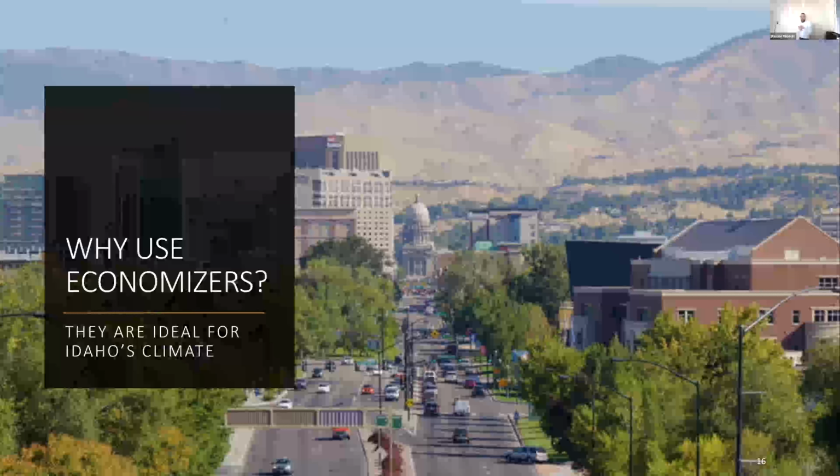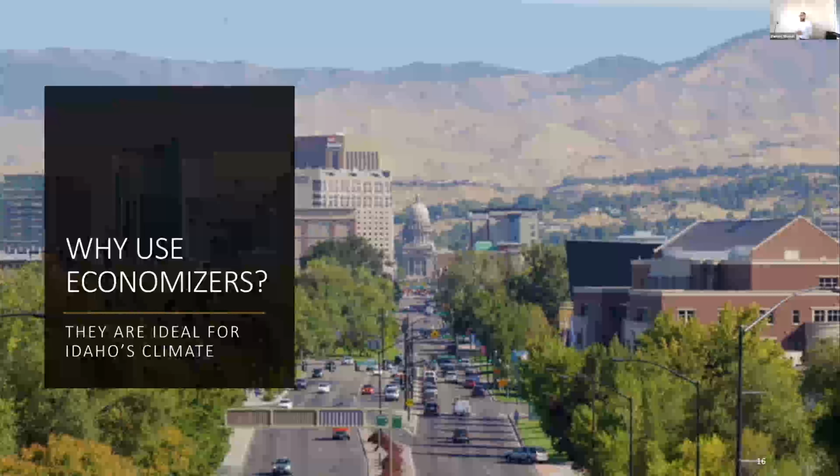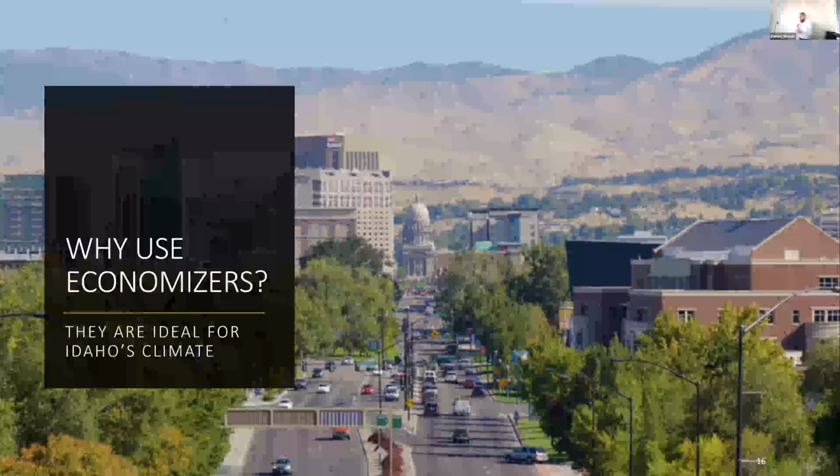Turn it off. And the reason was, then we looked at Moscow weather, and it was actually really hot outside. But the sensor made it look like it was cold because the sensor had been installed close to the rose bushes and the sprinklers were hitting it every morning. And so it was cooling it down, making it think that it was like 20 degrees colder outside than it was. So they moved that sensor, that's all that it took, and then reactivated the economizer.